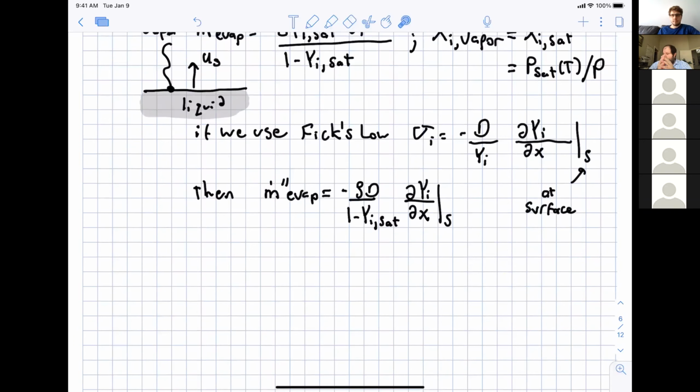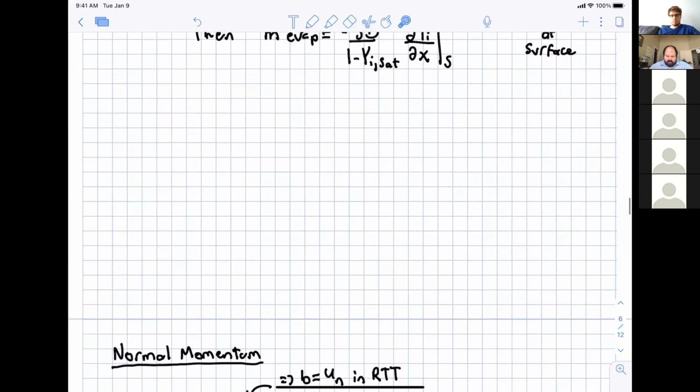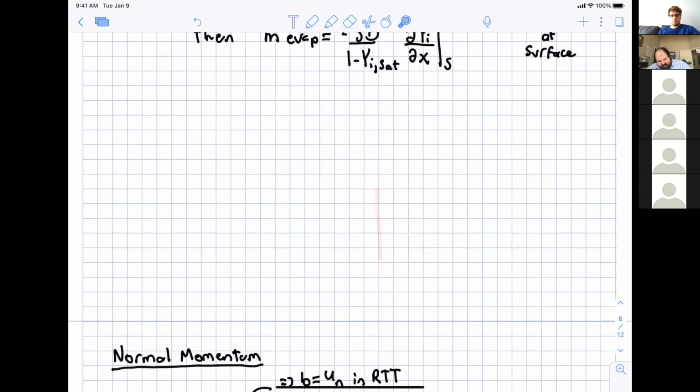So for the surface reactions, if you've got something like an end burning rocket motor, we would only care about the surface reaction if it needed something from the atmosphere in order to create the reaction? No, you could consider, and again, when we do propellant combustion, we're going to go over this quite a bit, but say we have a burning stranded propellant, you can draw a little control surface on the surface, and here you would have, say, RDX going in, and going out, you have a whole bunch of different species.